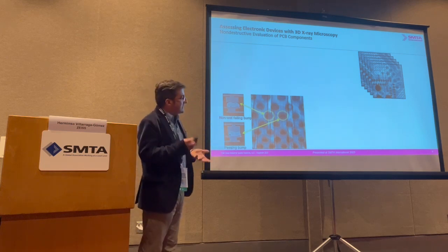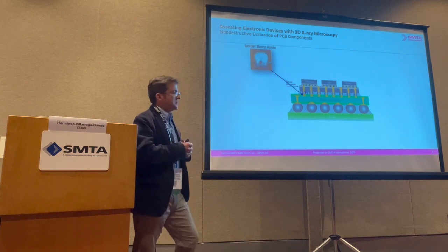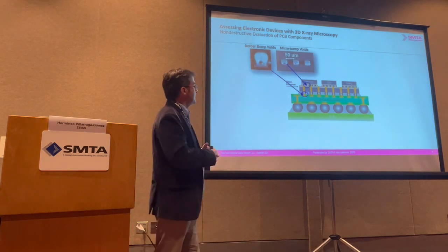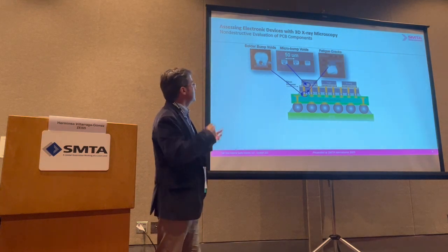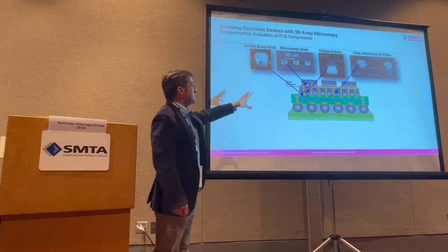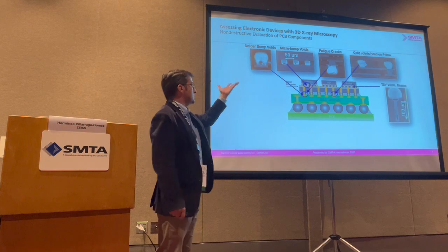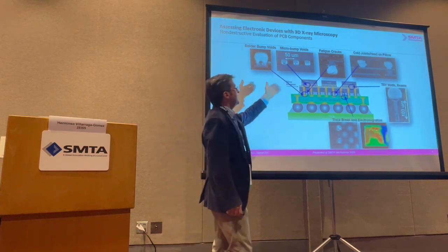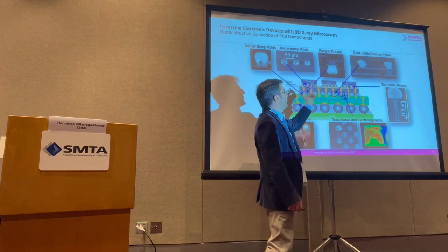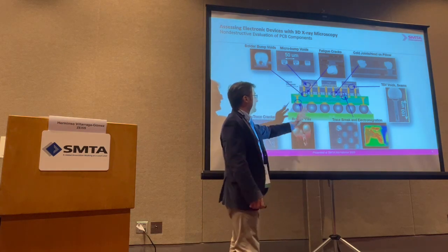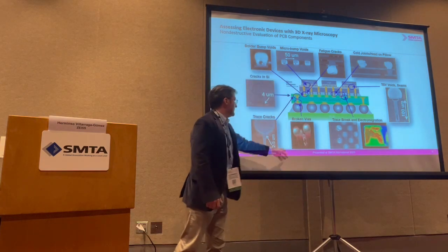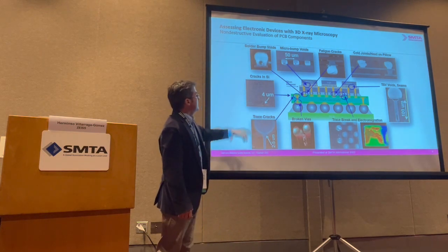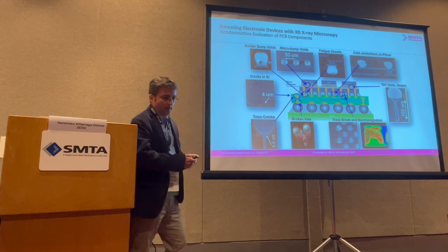That's what makes 3D really useful, because it gives us the full information of the volume that is inside of the part. And that's how you can inspect BGAs or PCBs, for solder bumps, micro bumps, fatigue cracks, cold joints or head-on-pillow, traces of electromigration, broken tiers, traces of cracks or cracks in the silicon components of the PCB.